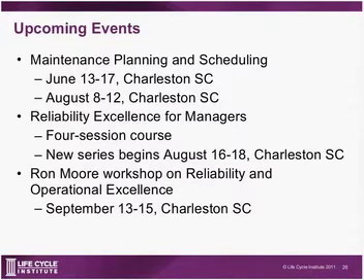And what I would suggest is to not just measure it at one point in time, but to continue after the action is implemented, to continue to measure your performance over time. So you can have a rolling week OEE, a rolling month, a rolling year to date, a rolling quarter, all those things, so you can see how your OEE is trending over time and put that in terms of dollars.